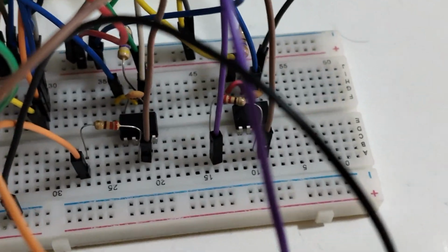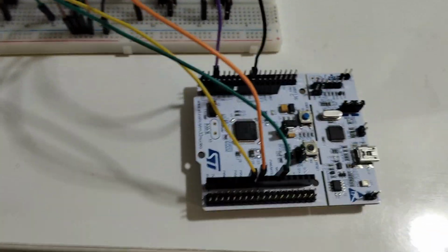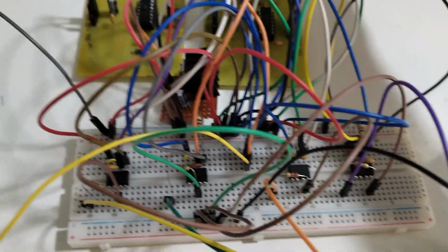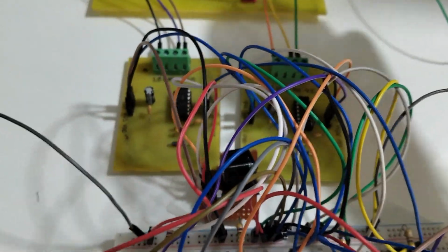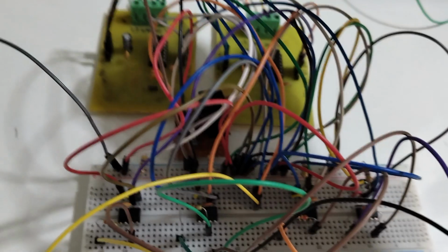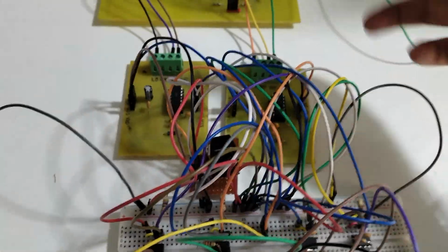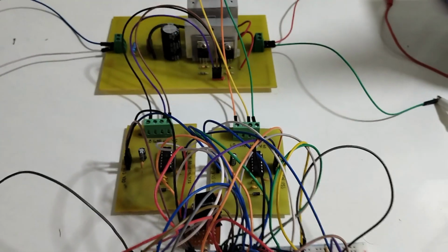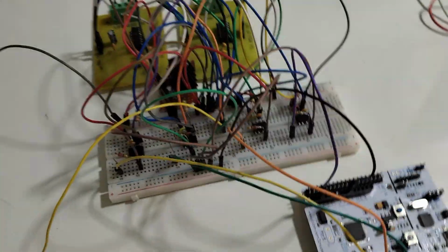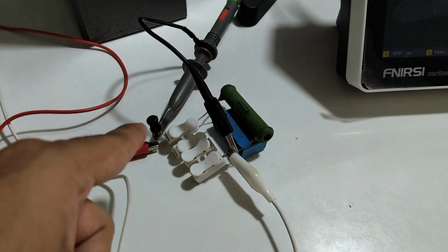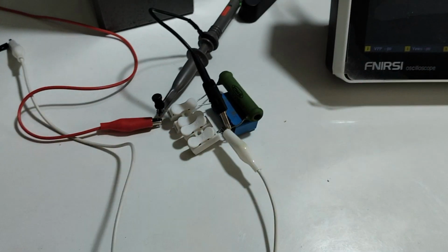So now there are two more, and now all four of them are going from the microcontroller to the optocoupler, and the outputs are individually going to each of the gate driver pins. So there's no giving the diagonal to this and this anymore. So now we're independently controlling all four switches. So I'll just turn it on, and same as before, 100 ohm, 1 millihenry and 1 microfarad filter.